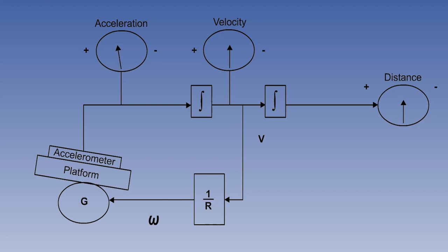So let's show this false acceleration on our meter. This acceleration will be passed to the first stage integrator, where it will be integrated into velocity, and then to the second stage integrator, so that it will be integrated into change of position. At the same time, the velocity is passed back along the V over R feedback loop.